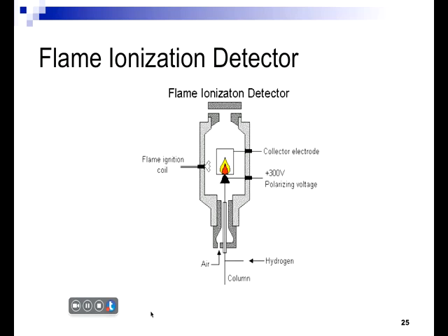And this is kind of how they work. You'll take the gas and vapor and you'll put it on a flame and burn it. That's what the flame ionization is. And you'll create ions, and the ions can be collected at the collector electrodes, create a gradient, and measure that. And so it's similar to how you measure the ions that are produced from photoionization detectors.